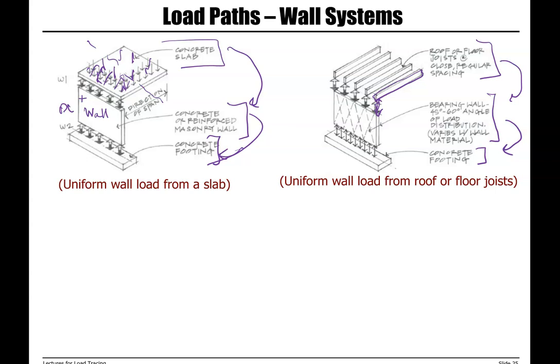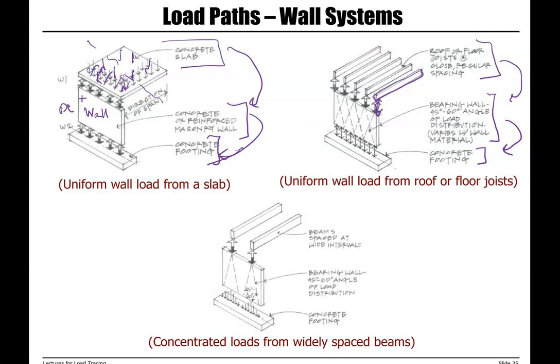And we will have a uniformly distributed load transferred from the bearing wall to the footing. And the third one is when we have beams spaced at wide intervals. So the path is still the same from beam to bearing wall and from bearing wall to the footing.